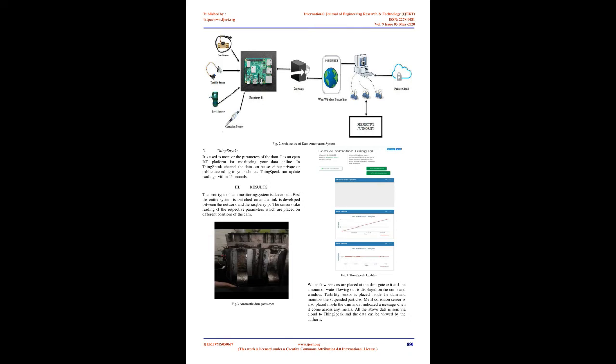Based on this information, the countermeasure of epoxy coating can be done to maintain the good health of the dam gates. See flow chart. The output of the sensors is constantly monitored and updated on the server and displayed on a web page. Analysis can be done by using stored data, and the system is programmed in such a way that the dam gates are automatically opened whenever the parameter exceeds the threshold value. The data collected can be monitored through a server page. This is shown in Fig 1.